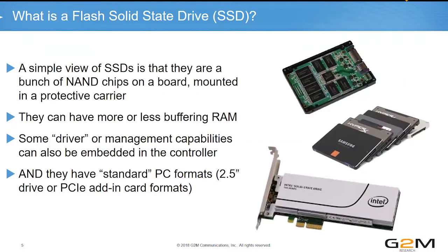So kind of starting out, one of the first questions I want to hit is, what is a flash SSD? This is not meant to be a rhetorical question. A real simple view is that it's a bunch of NAND chips stuck on a board with some sort of controller. You can have some amount of RAM, some have more, some have less, and that can impact performance. Some have management capabilities built into the controller, some don't. So that's the classical way of looking at what an SSD is. And there are a lot of different form factors, everything from 2.5-inch drives to PCI Express add-in cards to M.2 drives, and some new form factors that we'll talk about in a little while.